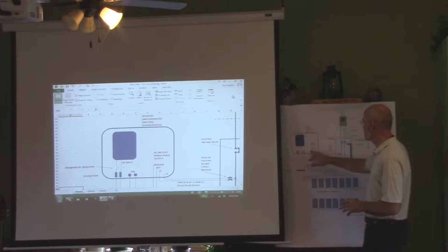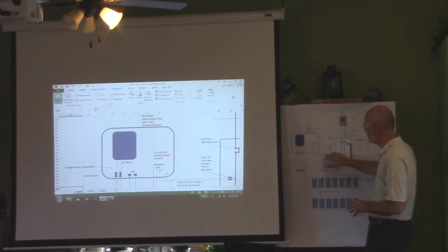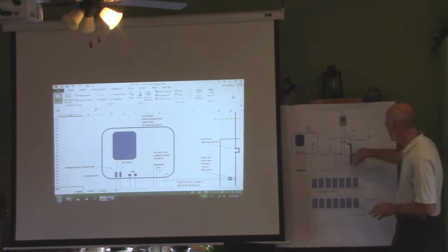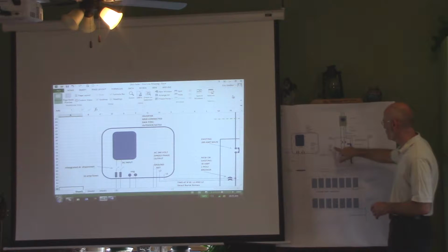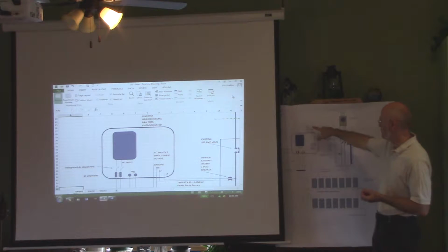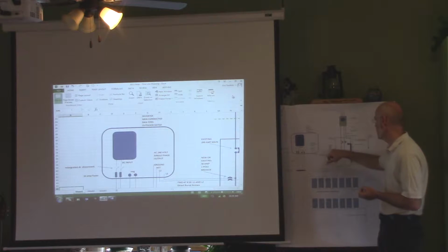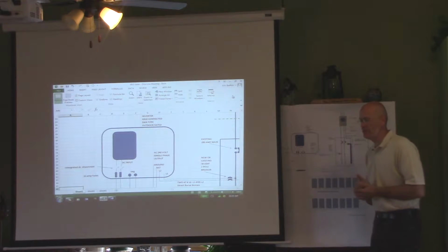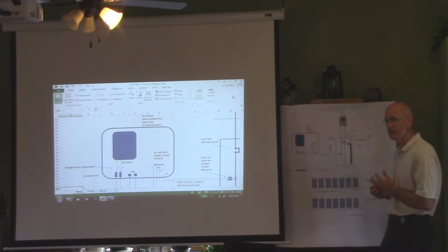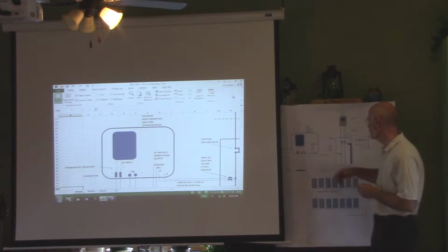So now that you've taken it from DC to AC, you got power coming here. This is your main power panel in your basement. And you're going to wire it to a 30 amp breaker, plus or minus. Could go 20 amps, whatever. Why don't we do that example real quick? What's 4,400 divided by 240? Okay, less than 20? Yeah, we can do a 20 amp breaker there or a 30 amp breaker.